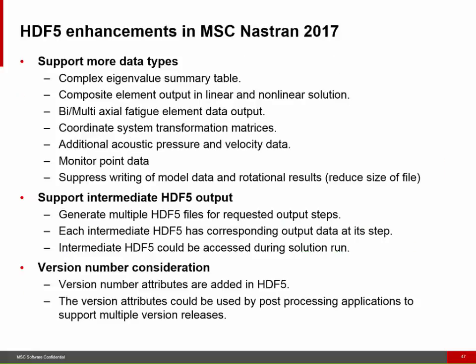In MSC Nastran 2017, we add a number of new data types like complex eigenvalue summary table, composite element output, more fatigue, more acoustics results. We also add monitor points, which wasn't there before. And we also have a possibility to exclude the model data and also to exclude the rotational degrees of freedom results. If you have very large file sizes and you're not interested in the rotational degrees of freedom results, you